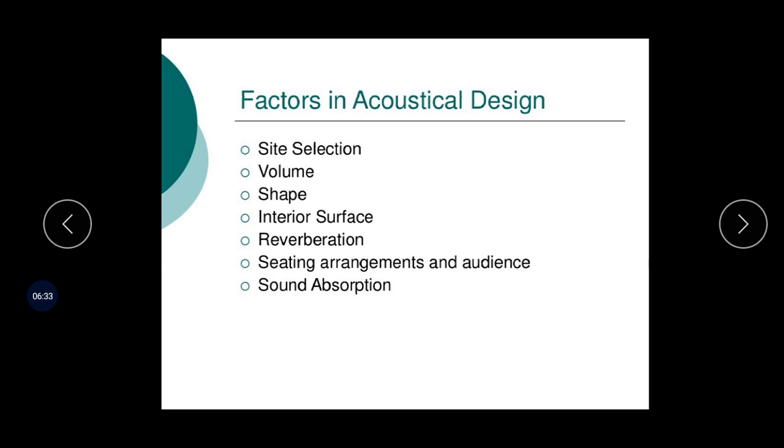If I want to add one more, some of the important sources of objectionable noise are automobile traffic on roads or busy streets, highways, railways, airports, and industrial establishments nearby your site. In fact, the site selected should be in the quietest surroundings. First, try to select a site in a quiet environment. This is the condition, with the other requirement that intelligibility of speech and total quality of music are not affected.